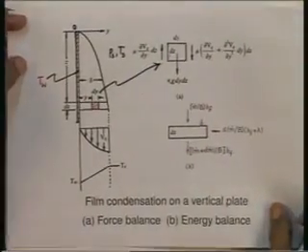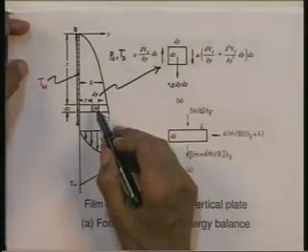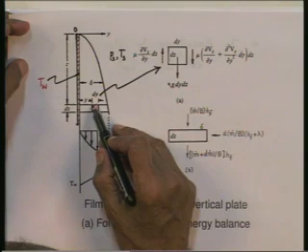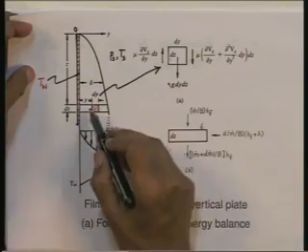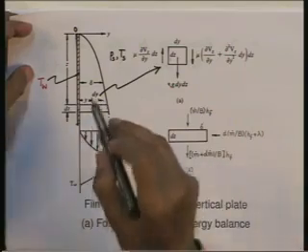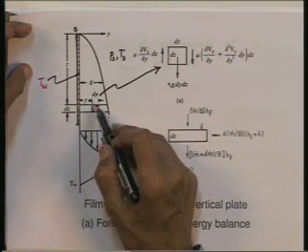let us look at the sketch again now. At a distance z, I want to know the mass flow rate. Suppose I ask you what is the mass flow rate flowing through this area dy, and in this x direction it is b. So, b into dy is the area. The velocity is v z and the density of the liquid is rho.